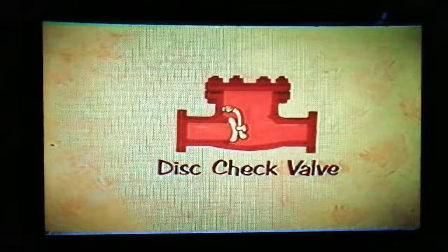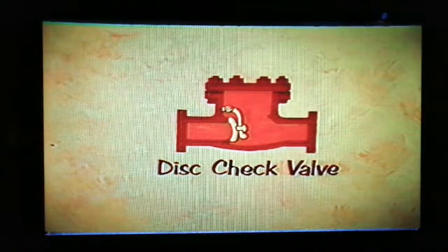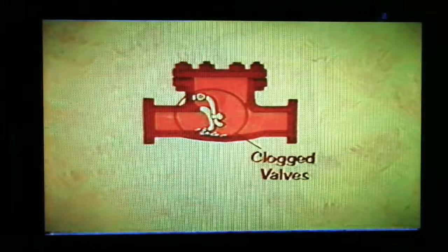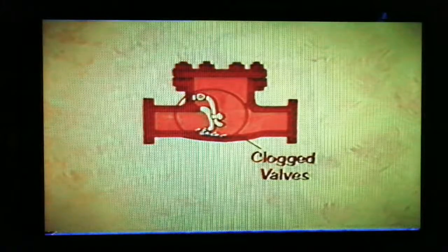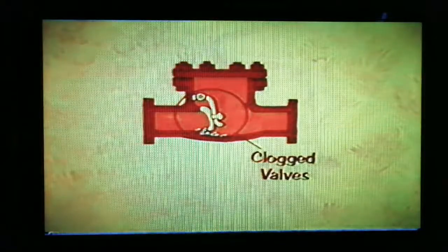Tilting disc check valves, including swing disc and flat types, keep losses low with almost straight-through flow. They close dependably with the slightest flow reversal or even zero flow. But a tight seal is undependable, especially if the valve happens to close against a foreign particle.